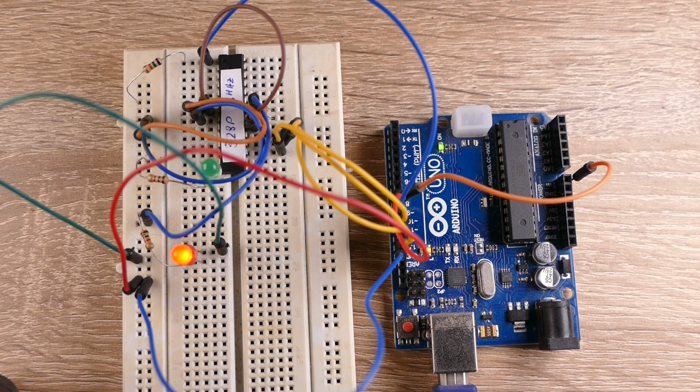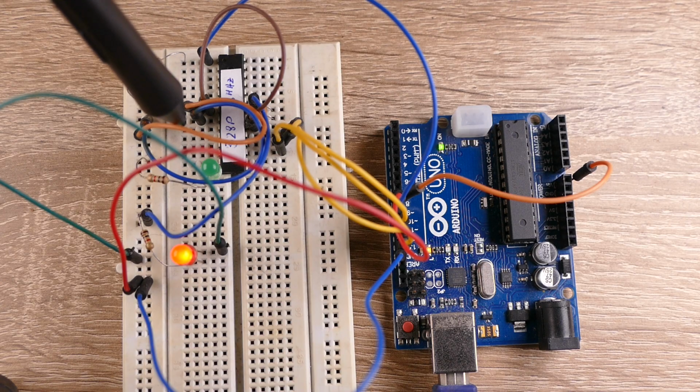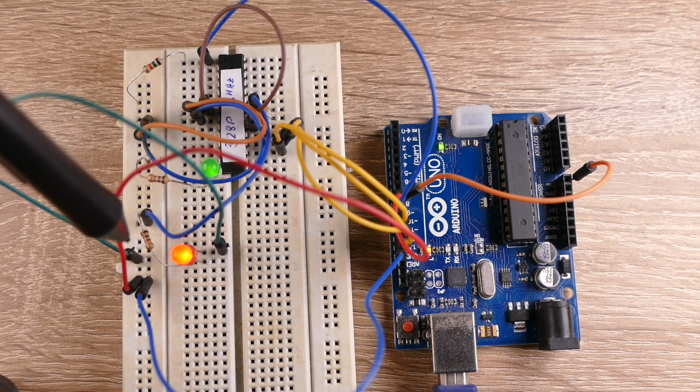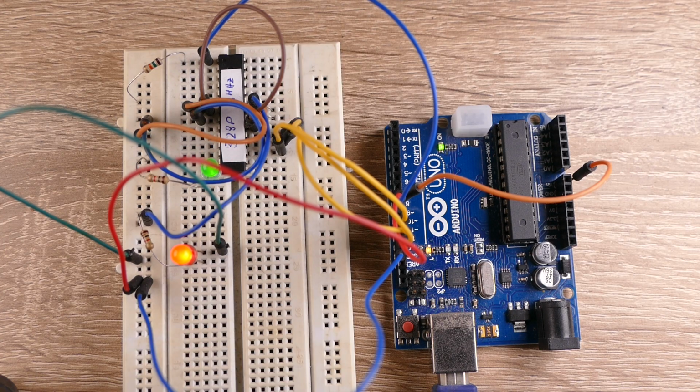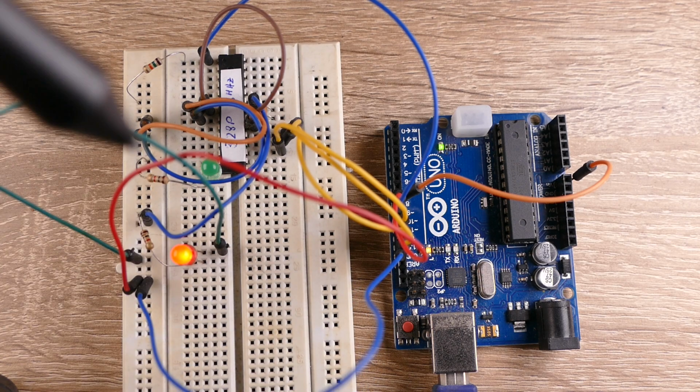I have here a setup. This is my DebugWireDebuggerProgrammer. This is my 328p, currently running on 8 MHz. I attached a green LED to port B0 that is blinking. This red LED means that power is currently supplied to the board. I have here a 15 kilo ohm pull-up resistor. And what are my connections? The yellow ones here are my ISP connections. This is my debug wire connection. Power also comes from one of the data pins. And this is ground.